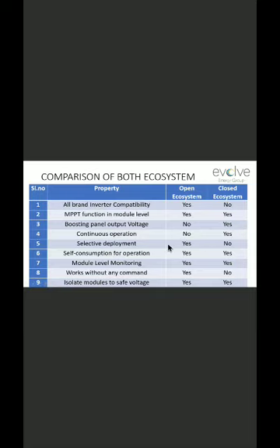In a closed ecosystem, it needs to work because it needs to give a certain voltage to operate the inverter or to deliver the power on the AC side. So it is continuously operating. When you are continuously operating the power electronics for 25 years, when you are thinking about a plant life of 25 years, you are losing the power electronics efficiency, right? No power electronics will be able to operate continuously for 25 years in the solar tree. So it has a disadvantage.